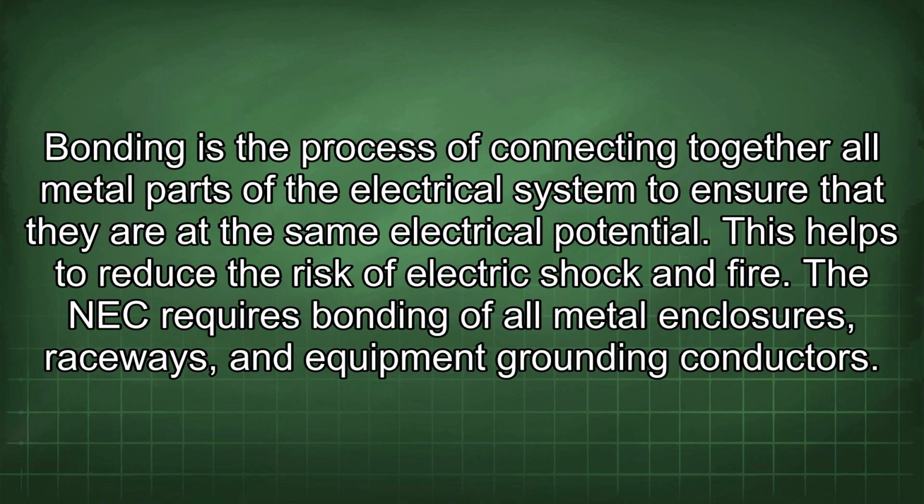Bonding is the process of connecting together all metal parts of the electrical system to ensure that they are at the same electrical potential. This helps to reduce the risk of electric shock and fire. The NEC requires bonding of all metal enclosures, raceways, and equipment grounding conductors.